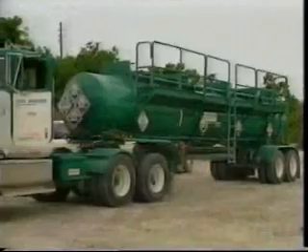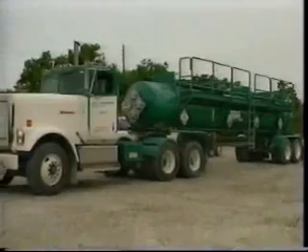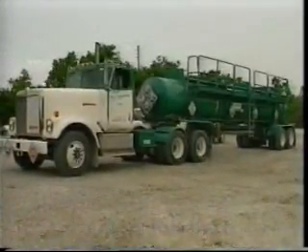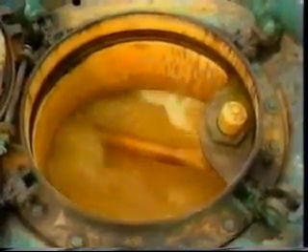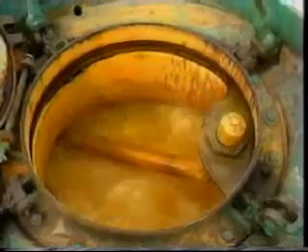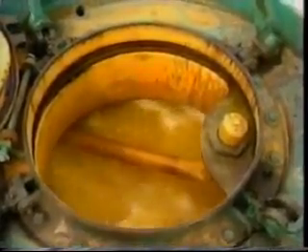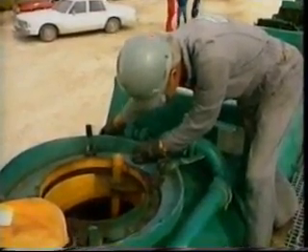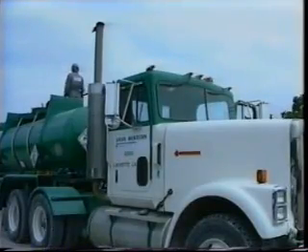The most important feature of this transport is the diesel-powered pumps used to remix acid and additives that may have segregated in the acid tanks due to density differences. The pumps force air to the bottom of each compartment to effectively mix the contents. This internal circulation is imperative to ensure complete mixing of fluids and should be done just before the acid is injected. Many service companies do not do this on a routine basis, so the engineer must specify this procedure in the original job proposal.